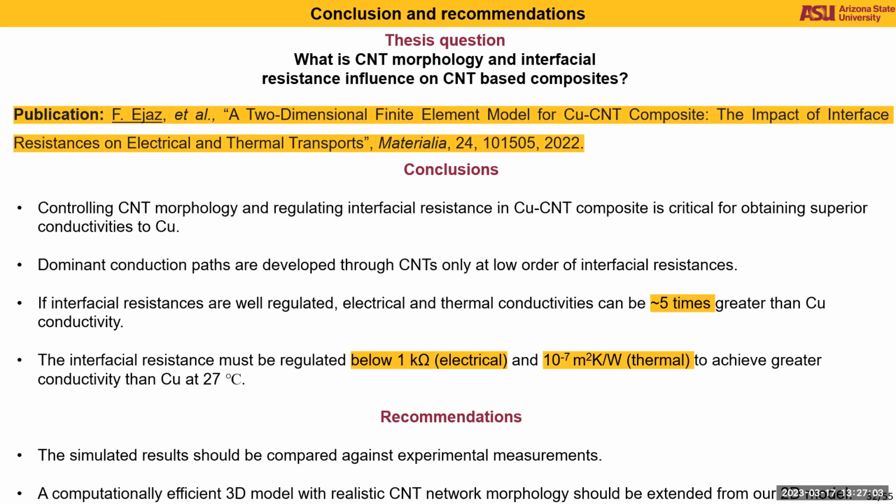So for our thesis question, what is the CNT morphology and interfacial resistance influence on CNT-based composites, we answered it with our publication in Materialia Journal back in 2022. And in conclusion, we developed a two-dimensional finite element model that basically provides us insight into the current and heat flow physics in the microstructure.